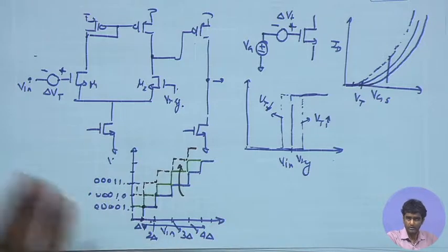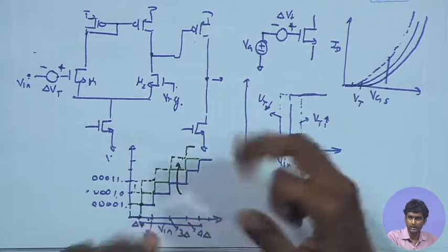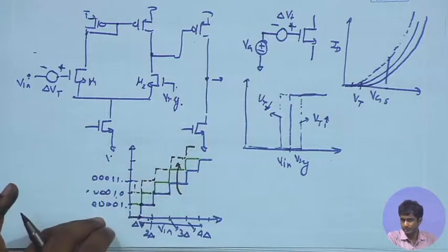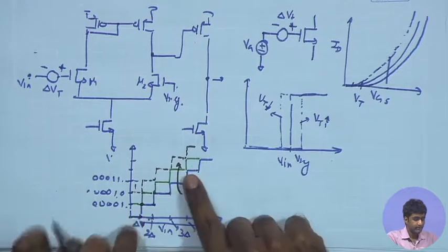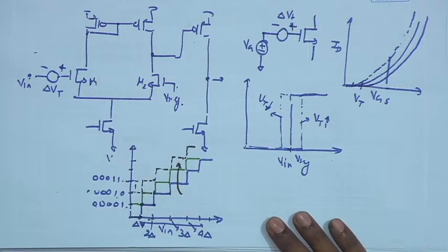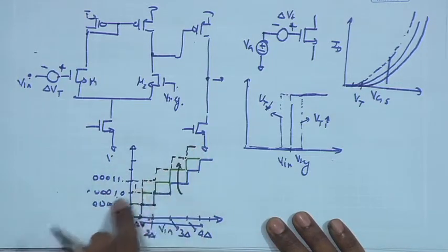So, that is one disadvantage, and another disadvantage is that the digital word recorded is higher than the expected exact values. So, if I am say having only one comparator, then this is occurring as an offset in the overall amplifier or overall ADC characteristics.